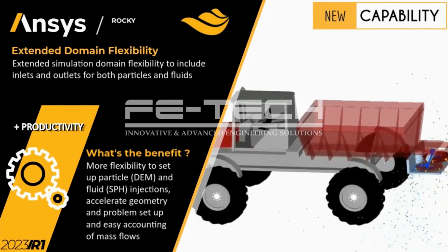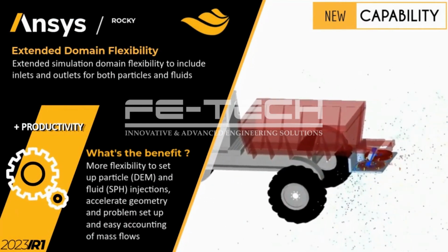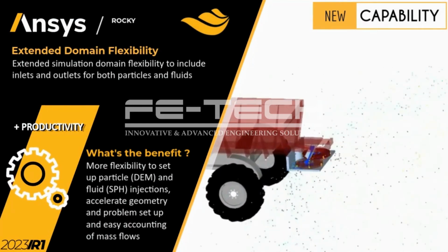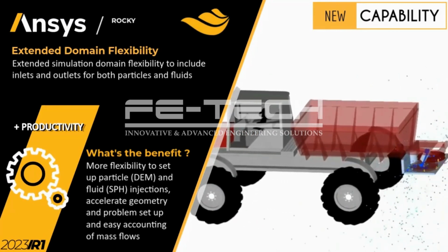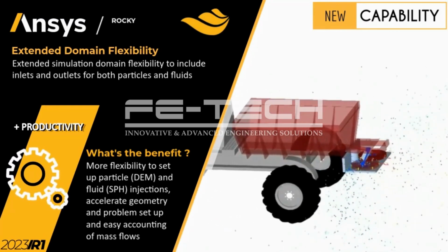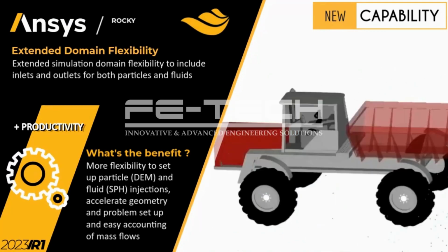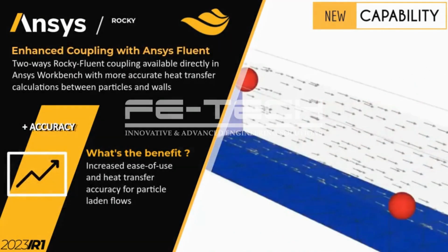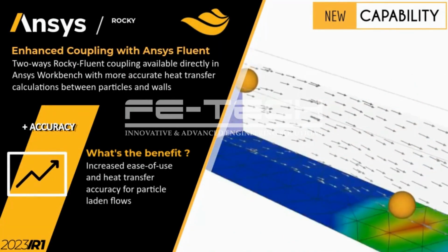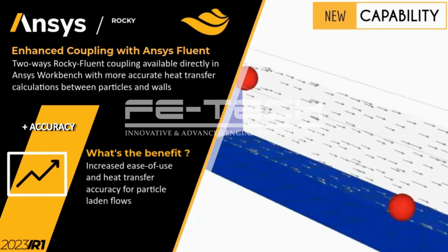And the simulation domain flexibility has been extended to include inlets and outlets for both particles and fluids, providing more flexibility to set up DEM and SPH injections. And the two-way Rocky Fluent coupling is now available directly in ANSYS Workbench, with more accurate heat transfer calculation between particles and walls.